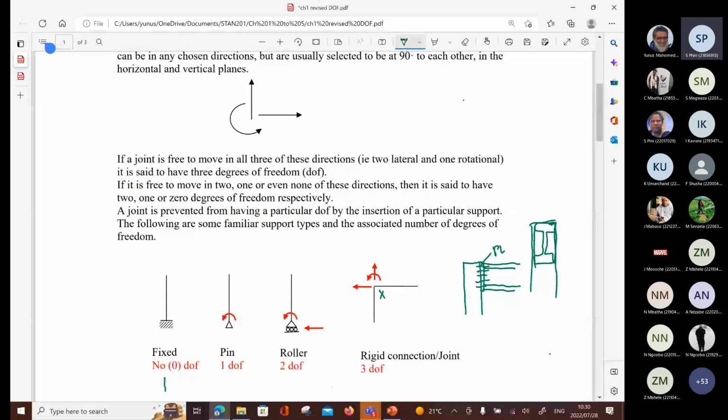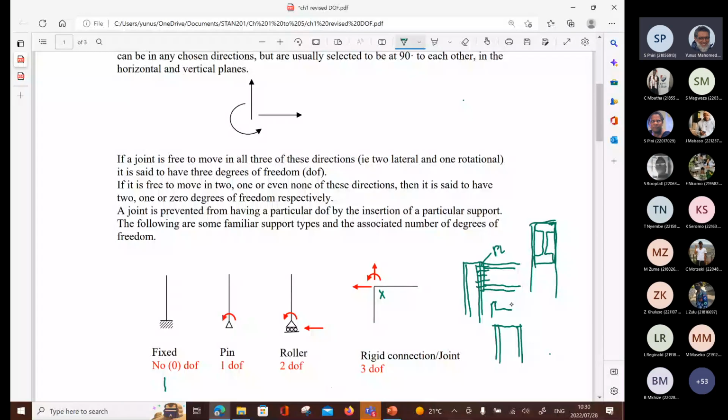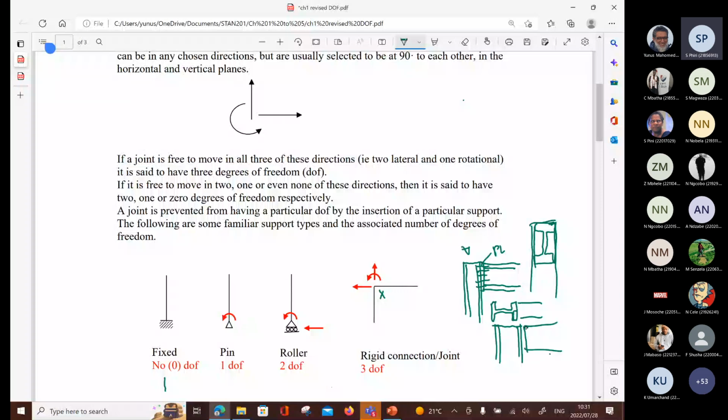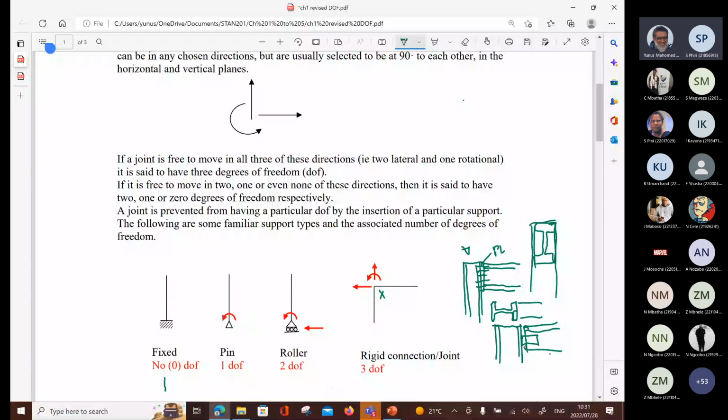And then your column in this case, you'll have a gap. You can have an end plate if you like, but you leave a gap. You'll put in a cleat here, and a bolt there and a bolt on that side. Are you with me? Okay, so you'll have a connection like that. All right, so that'll be a pin, but this one is rigid, so we can do this connection rigidly. Okay, so this is a rigid connection.